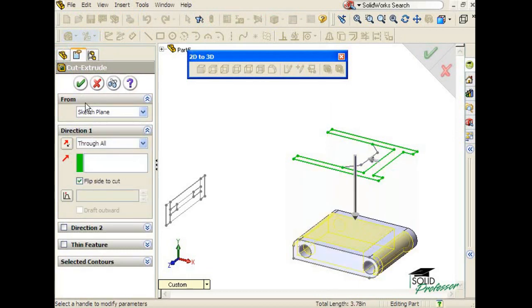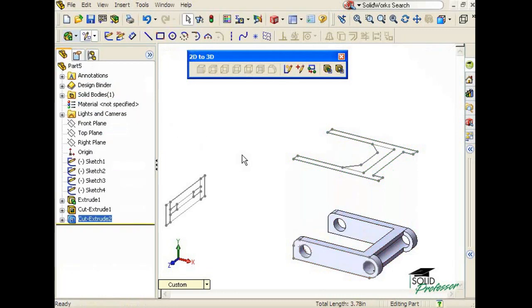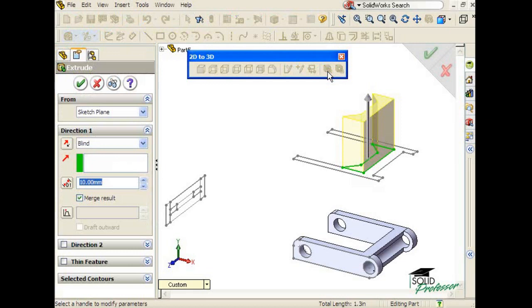All that remains now is to create a rib as shown in the top view. Notice the thickness of the rib is shown in the left view. I'll select the profile from the top view and click Extrude. I don't want the material to be added from the sketch plane as the preview indicates. I need the material to be added from the point shown in the left view.